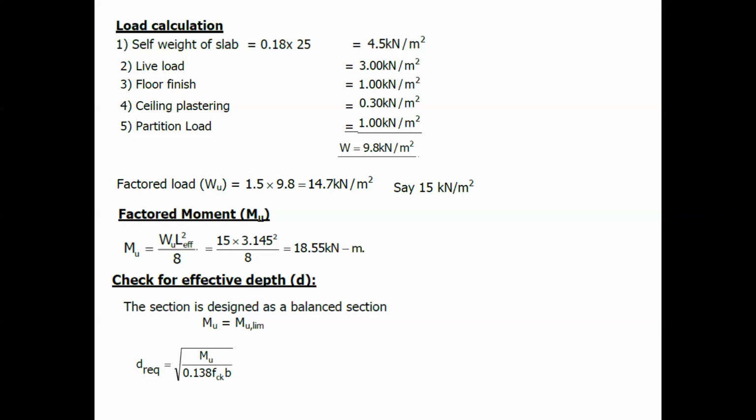While designing a slab, always consider b per meter, that is 1000 mm. Is that clear? Any doubt? No, sir.